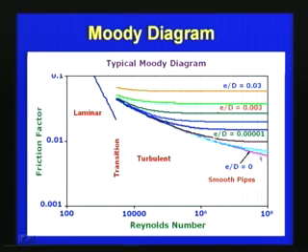So, this is the lowermost curve, and depending upon the Reynolds number, we can obtain the friction factor with respect to various ratios of e by D. This line is for laminar flow, and this range is for the transition. The Moody's diagram is commonly used to find the friction factor for the turbulent flow region, that is where we commonly use this friction factor f. Curves are given for various e by D ratios as shown in this slide.